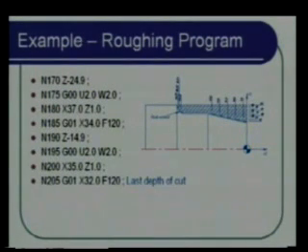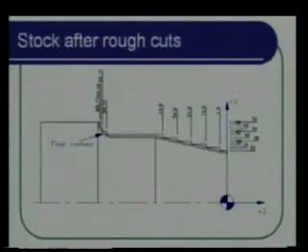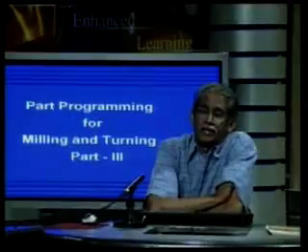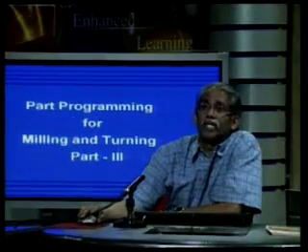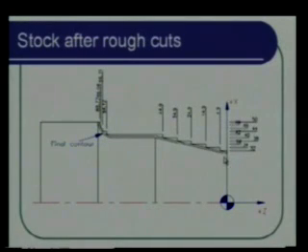So that is the last depth of cut. So that completes it. When I remove all the depths of cut, that is the roughing cuts, what you notice is the material that is left out here. So you can notice this is the left out material.